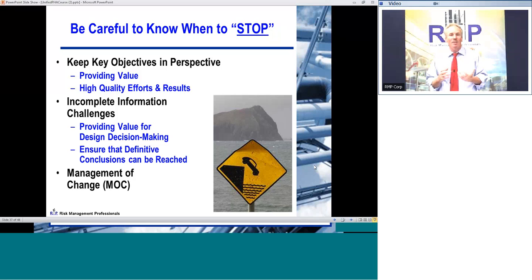management of change, how do you structure this, and if there are a lot of changes, how do you manage that? A key thing is if you've structured this properly, if your HAZOP is organized, if you've properly partitioned the work, starting and stopping should not be difficult. All right? If you've reached the limits of your knowledge, stop, but have it structured so you can pick it up easily later on and complete the safety evaluation, the HAZOP that provides this design formulation and evaluation framework, at a later time.